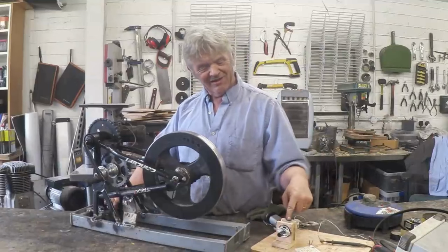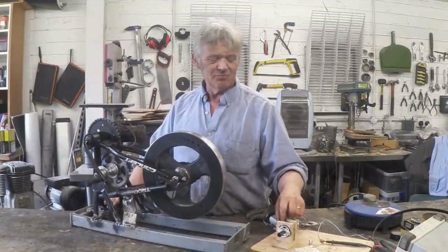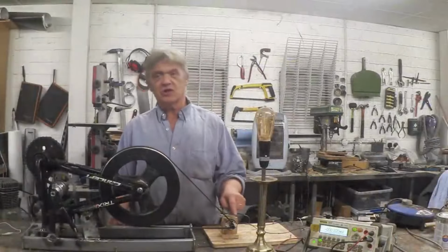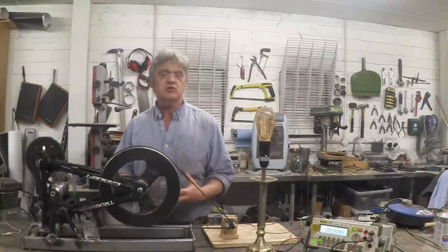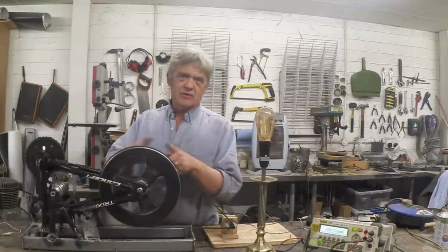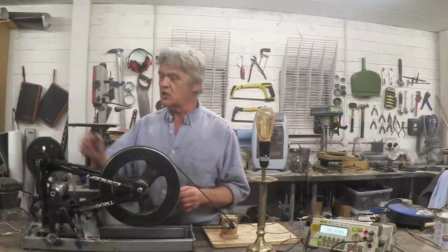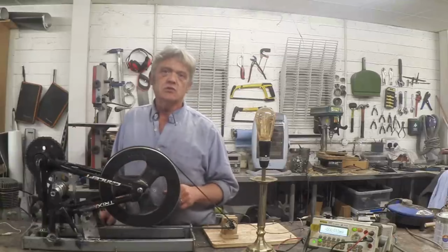So here is my little food blender motor that I bought for £1 and that I used in previous videos. Let's get that connected. Okay, so I've used a drive belt to connect it to the exact same motor we used in 1192, because what we're interested in, remember, is the relationship between speed and voltage. And this is about 28 centimetres, that's about 2 centimetres, so we've got a 14 to 1 gear ratio, and a 5 to 1 gear ratio here, giving us around about 70 to 1.